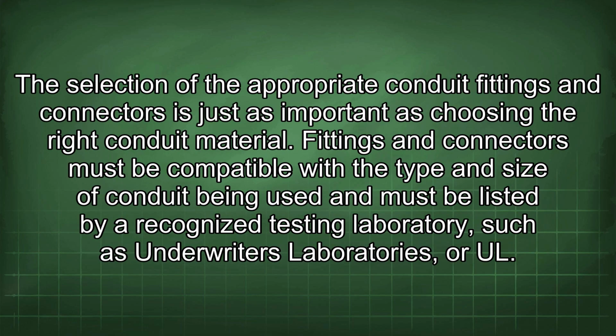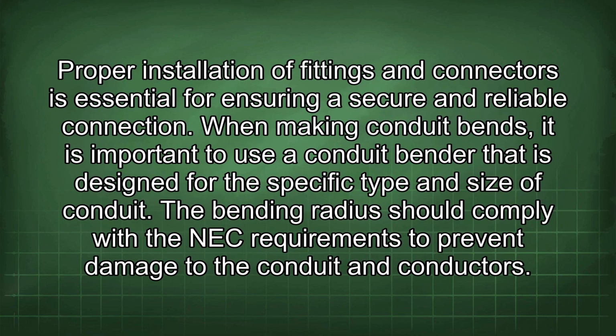The selection of the appropriate conduit fittings and connectors is just as important as choosing the right conduit material. Fittings and connectors must be compatible with the type and size of conduit being used and must be listed by a recognized testing laboratory, such as Underwriters Laboratories or UL. Proper installation of fittings and connectors is essential for ensuring a secure and reliable connection.